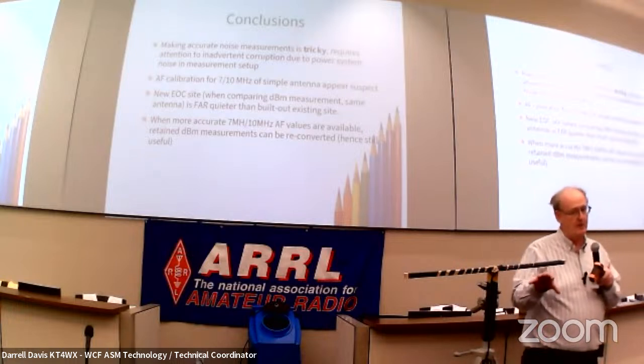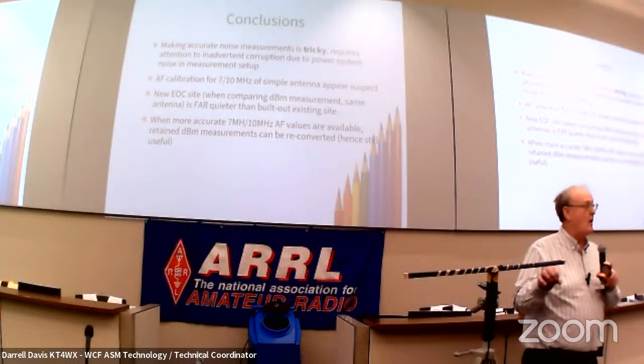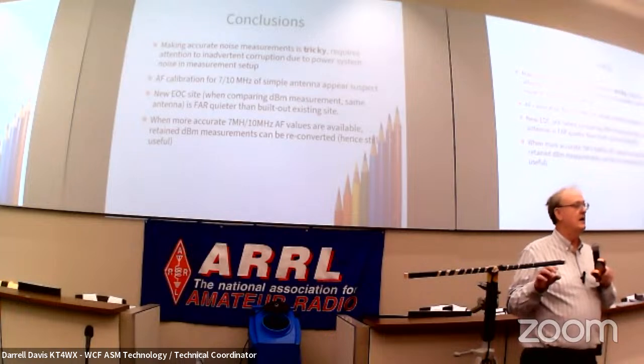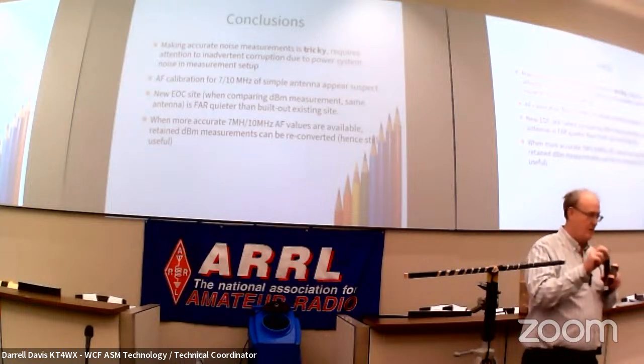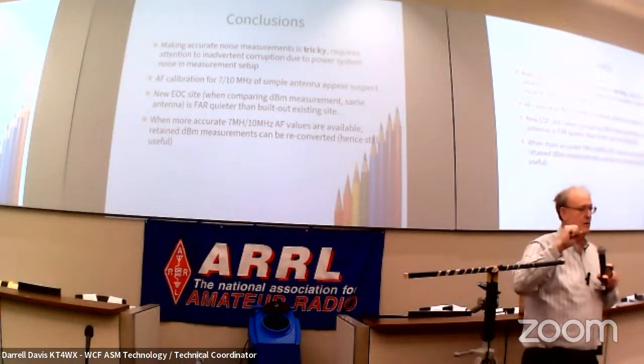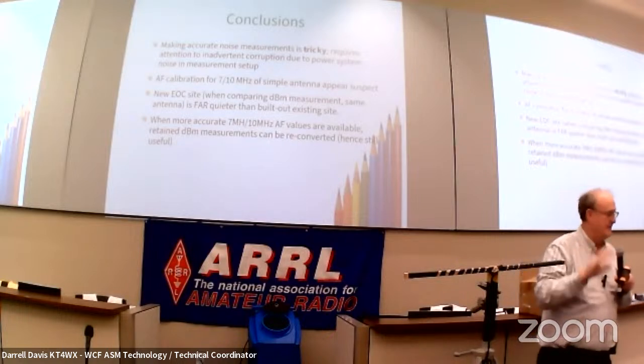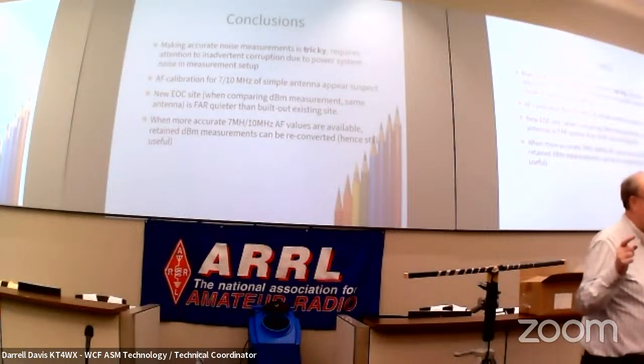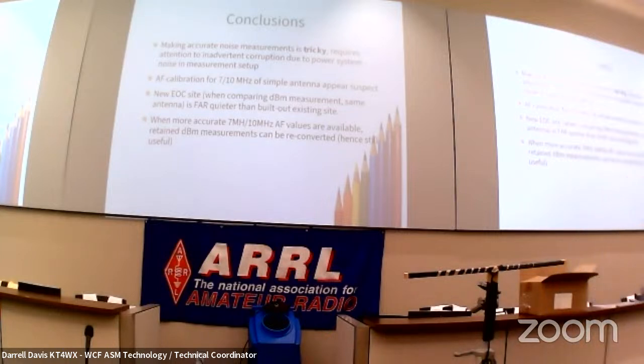Because we were able to quiet that generator. We quieted it once. It took us a MIF plus 2 or 3 toroids, 100 feet of extension cord, and it disappeared. You couldn't find it anymore. It was gone. We had the antenna set up in my garage. We were using some ham sticks as the antennas. And after we were done, it was gone. The S meter was not moving. We could turn the generator on, nothing.